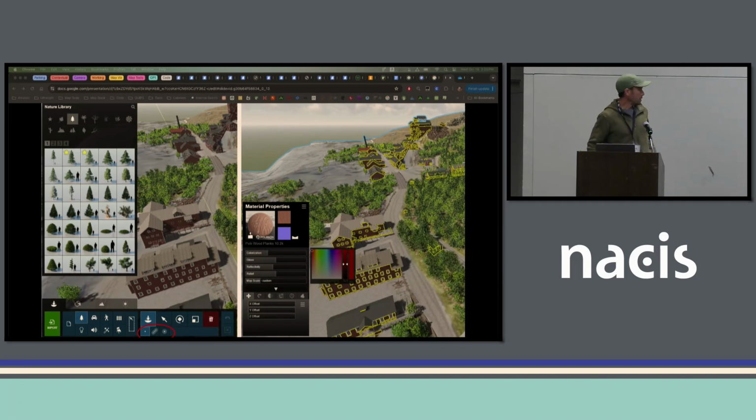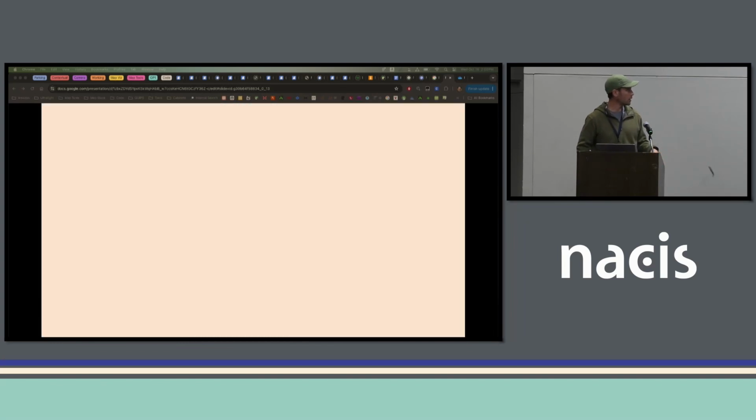Just quickly run through some of the features here. So here you can see some of the asset library, lots of conifers here, and I've circled down on the bottom. You can also scatter all sorts of assets, whether it's rocks or trees, so you can do a linear scatter, you can do a circular pattern, and you can select like 10 different species of trees. So I can pick 10 different species of conifers, or I wouldn't do 10, but say 3, and then be able to randomize those on the landscape. Still have to go in and edit a lot of things manually to move them off of roads, move them off of trails. And then a lot of the final texturing is done in here as well. So I'll get some base textures in SketchUp, understand kind of what I want them to look like. But if I want diffuse models and bump mapping and some of the more fancy texture stuff, I'm going to end up doing it here in Lumion.